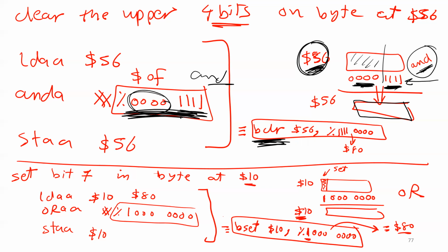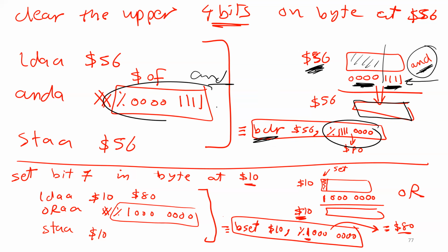That's why here is a mask. In the mask, you only need to mark the bits you wanna clear. That's why here, the bits you wanna clear, you have to put one. What I'm saying here, guys, because this confuses students, listen to me. If you use this instruction, I'm gonna use this number. However, if I use this one, I'm gonna use this number. Why are these two numbers different? Simply because what I'm doing here is different from here.